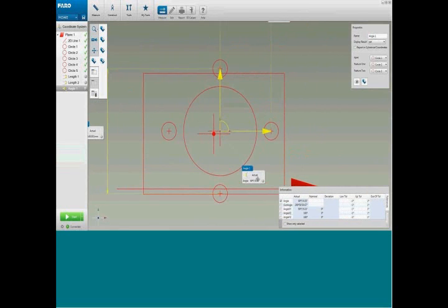Again, using the feature information here, we can enter normals, and we can enter tolerances, and you can see now the deviation is colorized depending on whether it is good or bad. Within tolerance, it will be green, and you will have a green tick. If it's out of tolerance, it will be red on the positive, blue on the negative.